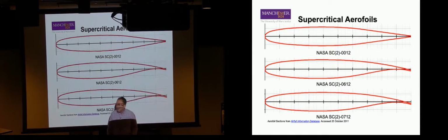By doing that, we generate more lift back here. They're aft loaded. It also means, what about our pitching moment? If we're generating more lift back here, what's it doing to our pitching moment? It doesn't move the pitching moment. Moments don't move on their own. What's the pitching moment at our aerodynamic center? Is it going to be more nose up or more nose down? More nose down. So aft-loaded airfoils, one of the downsides is they have more nose-down pitching moment that we have to counter.